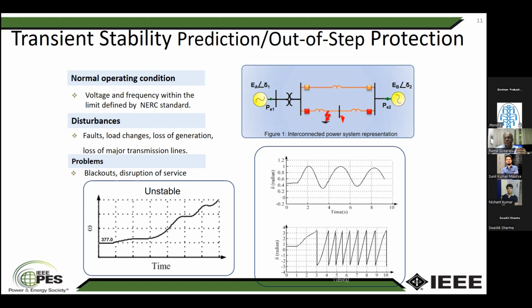That is where we are going to open up the circuit breakers. Remember that this is not an operation of the circuit breaker for a fault. For a fault, the restriking voltage is going to be about 1.3 to 1.5 per unit. So if you have a 400 kV system, you can find the corresponding restriking voltage, 1.3 to 1.5 times